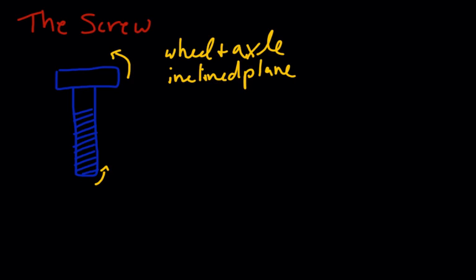When you have a screw, a lot of times you'll see stamped on the box of screws, or in a CAD drawing, something called a thread note. There are thread notes, so you might see something like this, a whole bunch of symbols and letters and things. There can be some other things too, but generally the way to read a thread note is this first thing is actually the diameter of the axle. So this diameter here would be like 1/2 inch.